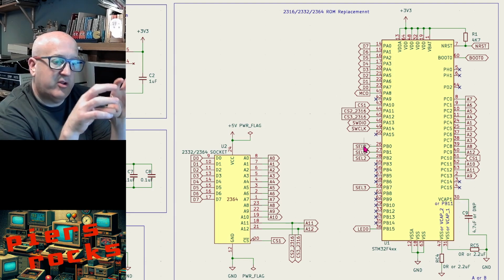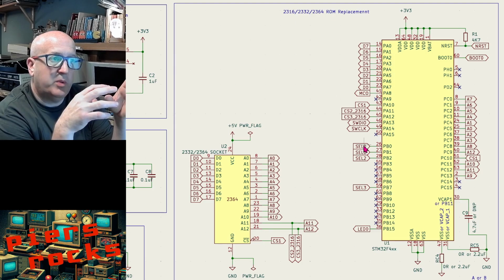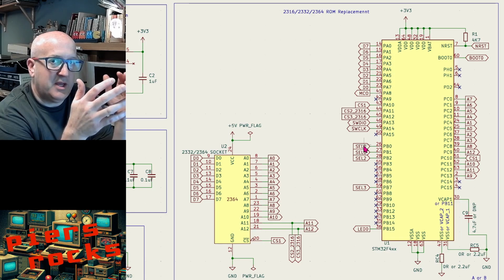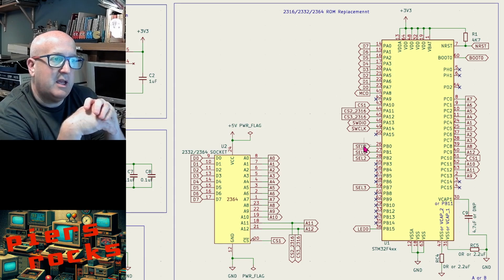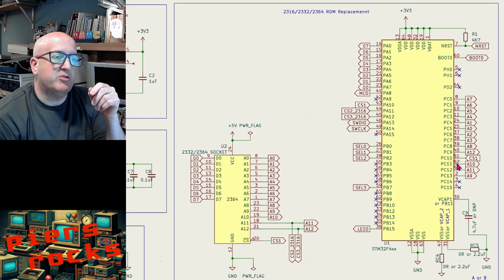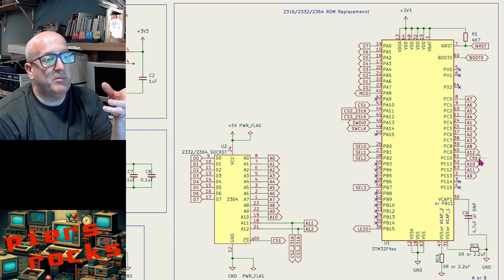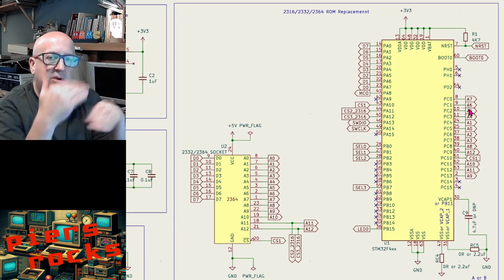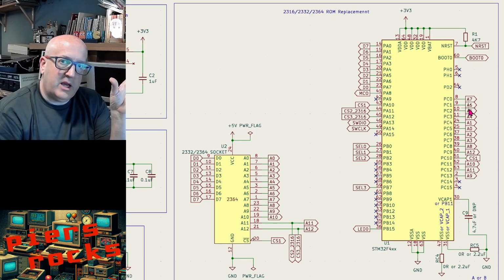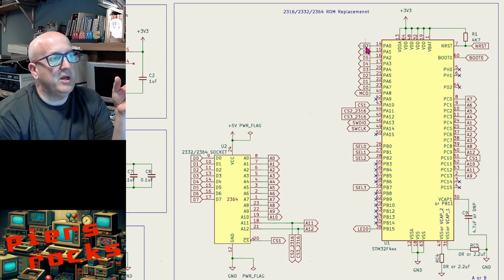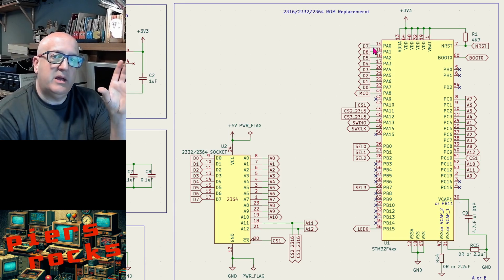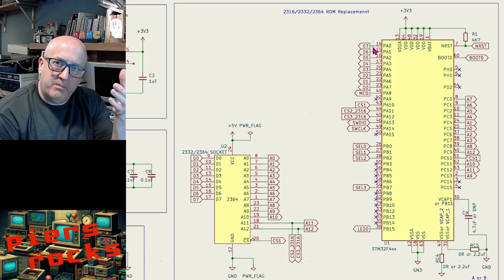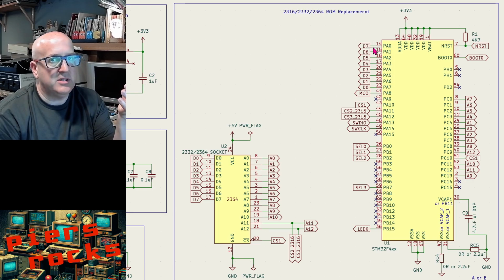When you've got this denser set of traces on such a small PCB and you're trying to hit the cheapest PCB manufacturing options with your trace widths, it's quite hard to fit everything in. You may have noticed that all the address pins are jumbled up, and obviously the chip select line is in the middle of those. You may be thinking, Piers, don't you need to rearrange those before you look up the byte in RAM? Similarly, you may notice that the data pins are the wrong way round, and therefore don't I need to flip the data byte around before I write it to the output register?